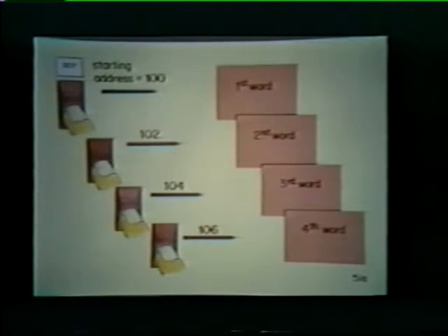After the first word is placed in the SR, we use the deposit switch to load this word into memory location 100. Now the second data word is placed in the SR and the deposit switch is raised again. This action increments the address by 2 so that the second word is stored in memory location 102. Thus, we can deposit data in successive locations simply by repeatedly raising the deposit switch. The load address operation has to be performed only once at the beginning.